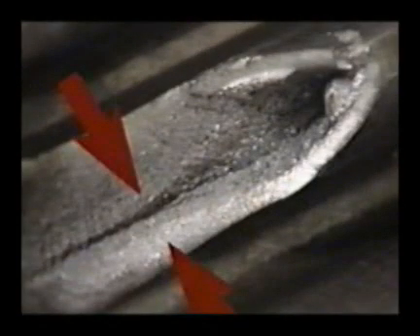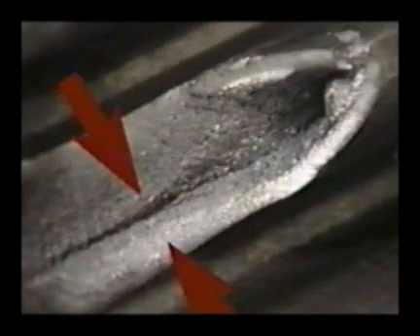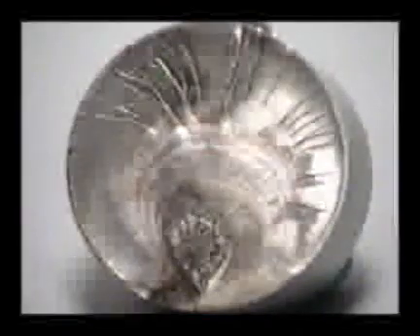Reverse bending can start two fatigue fractures, one on each side of the part, with beach marks running towards each other. Final fracture occurs between the cracks. Rotating bending produces beach marks that grow inward from the circumference. Final fracture occurs in the center region.